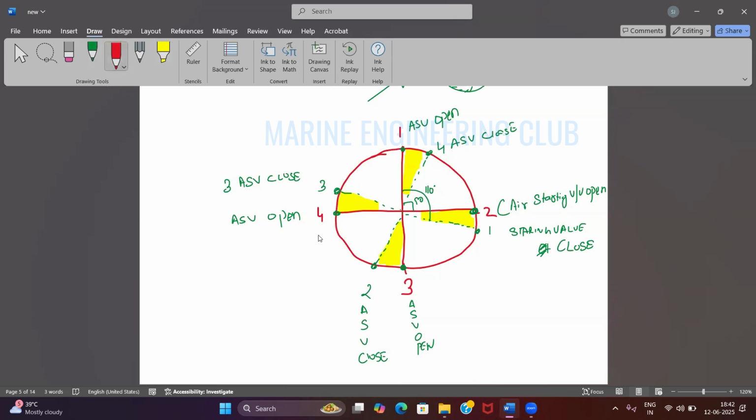See, in this part, if I take one of the shaded regions, number 4 is starting from here. Agreed? Yes, sir. In this part, number 4 is injecting air, but number 3 unit has not closed yet. It will close somewhere here at this point. So here I am getting 3 and 4 units getting air. If I consider this part over here, which unit is getting air? Only number 3. So in the complete revolution, all the units are getting air at any given point of time.